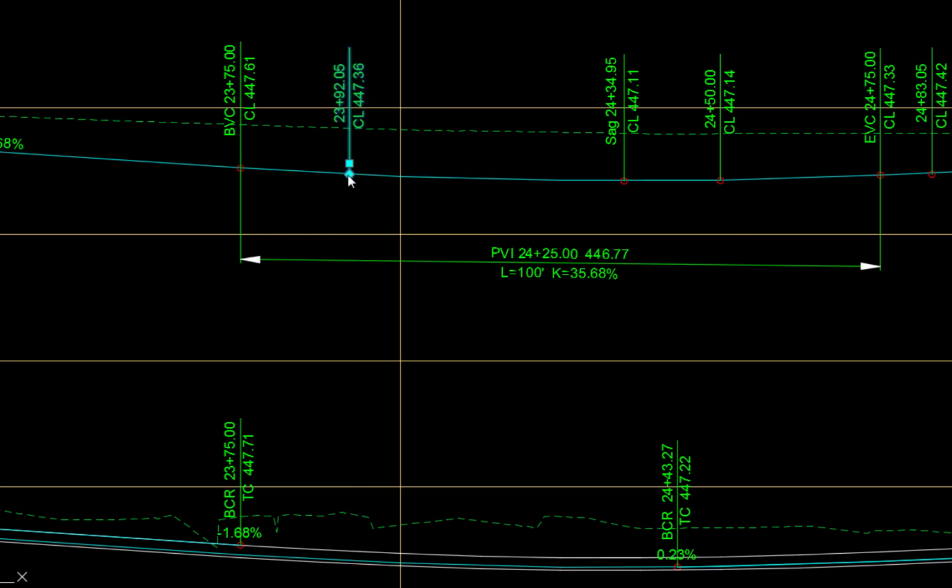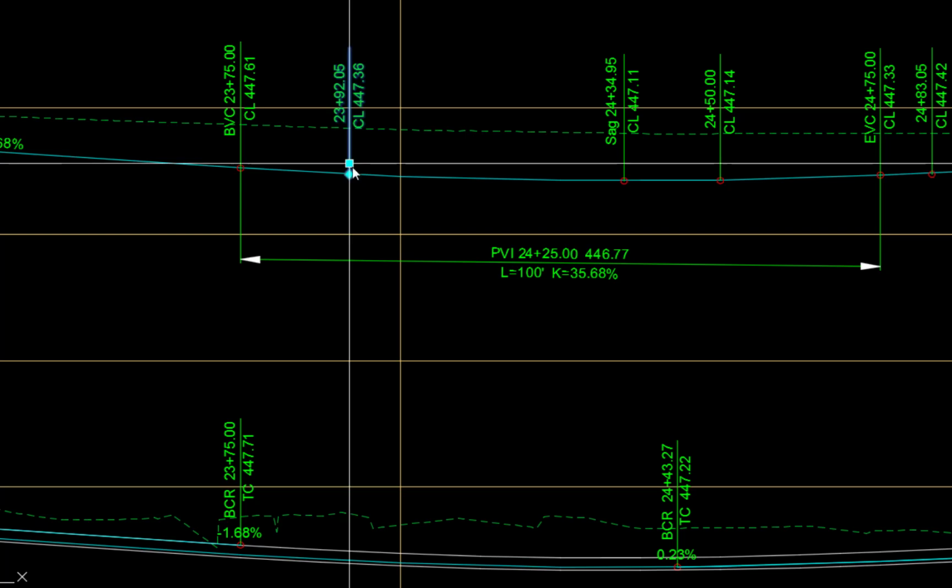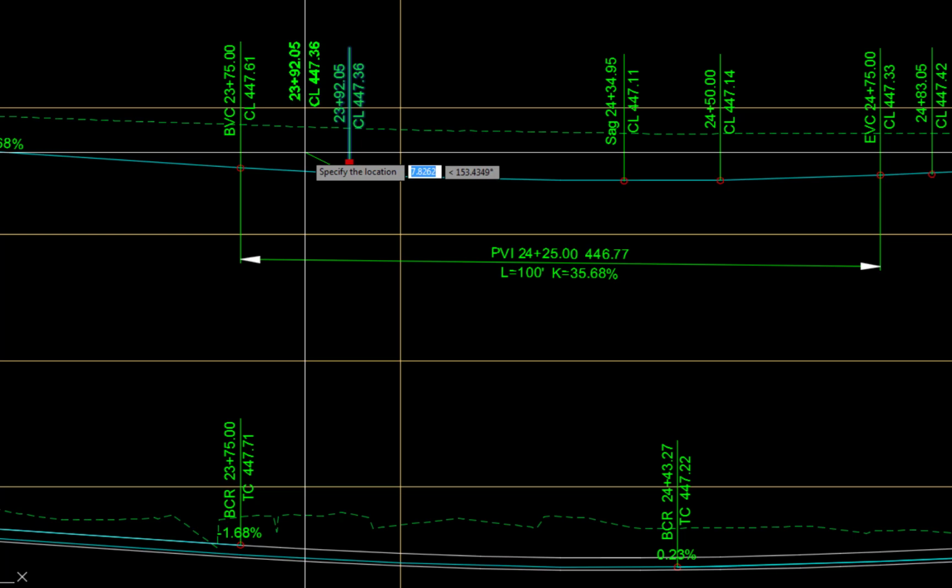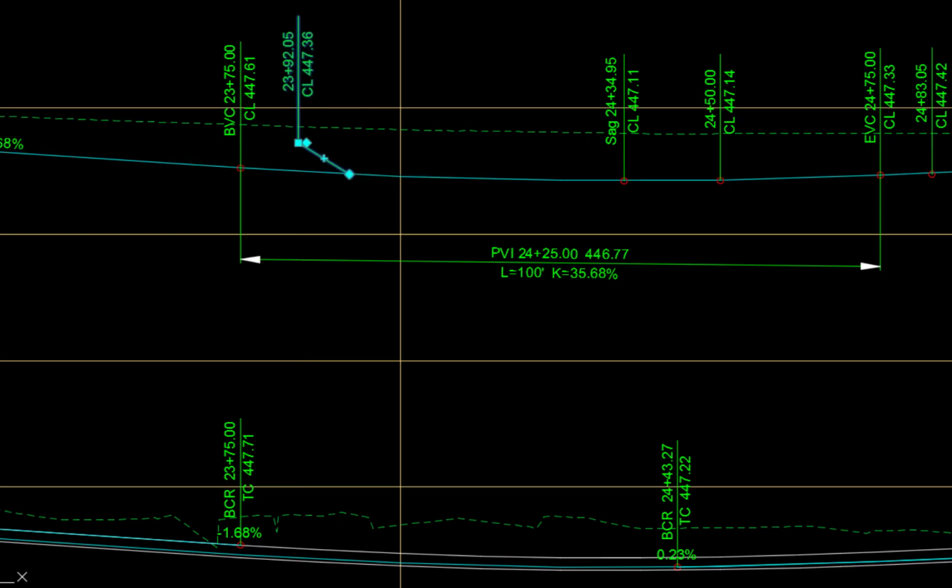The square glyph is used to change the location of the label away from the object. The object reference data contained in the label will not change as the label is moved. The appearance of this label and any leaders associated therewith at the changed location will conform to the drag state settings contained in the label style composer. The round glyph is used to restore the label to its initial default location and appearance. This particular label style does not contain a round glyph.